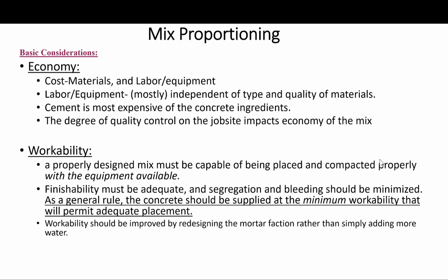But if the cement contents are too low, they will diminish the early strength of the concrete and will make uniformity of the concrete a more critical consideration. So these things you have to keep in mind. When considering economy, if you reduce the cement content, we gain in certain aspects, but on the other hand, we might lose. So that is the balance you have to make.